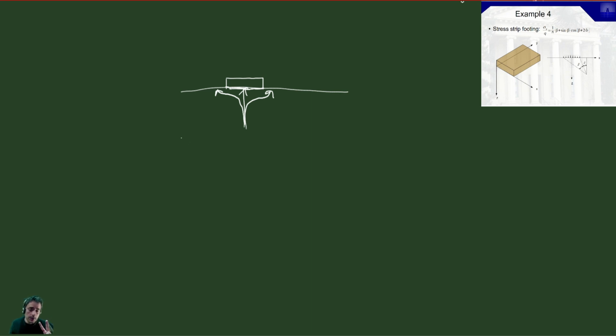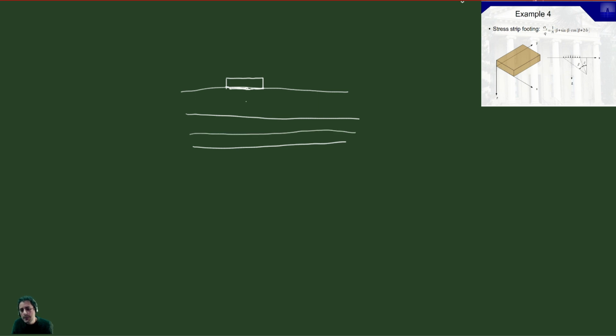Also, what the 2D consolidation model lets you do that 1D doesn't is that you could conceivably have a relatively uniform clay that might have little seams of, say, silty material like this that increase enormously the hydraulic conductivity in the horizontal direction.